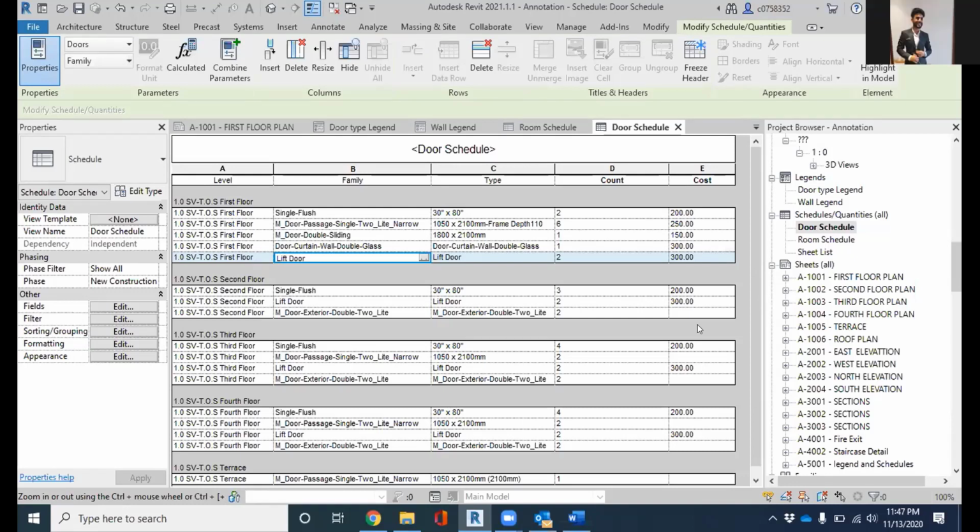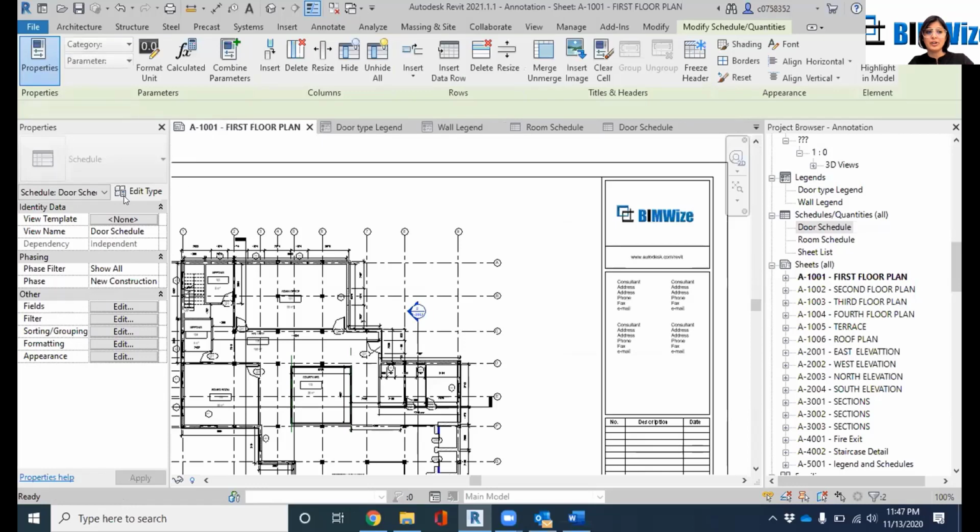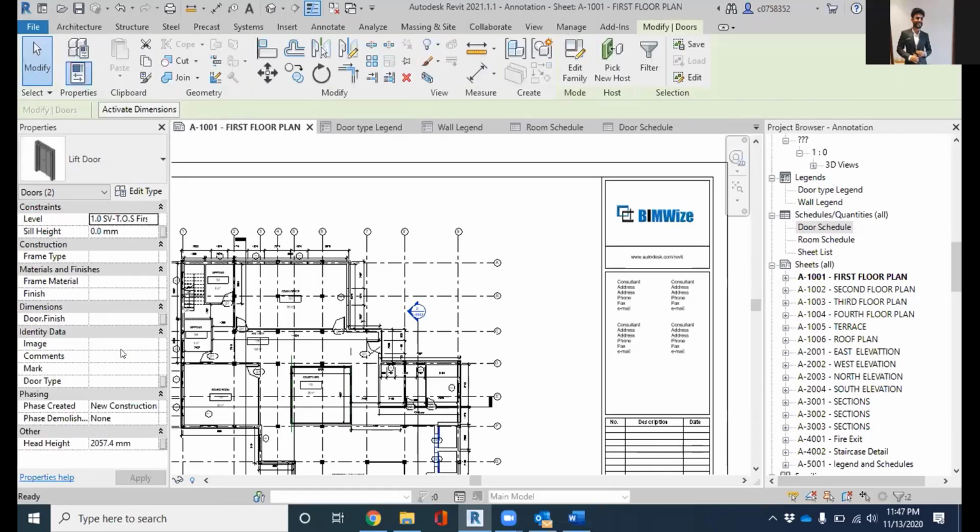Can we just, the presentation of the drawings are all similar in all the drawings. So can we change that? Like we want to change the type of the presentation lines, the section lines, even the tag. We can do that. Each view, we can have a different presentation style. And that you can change from your properties.